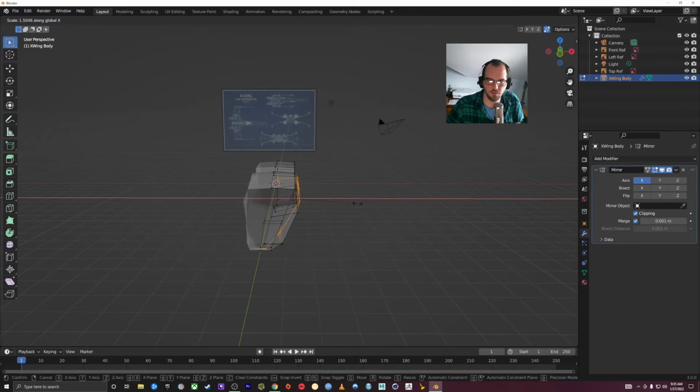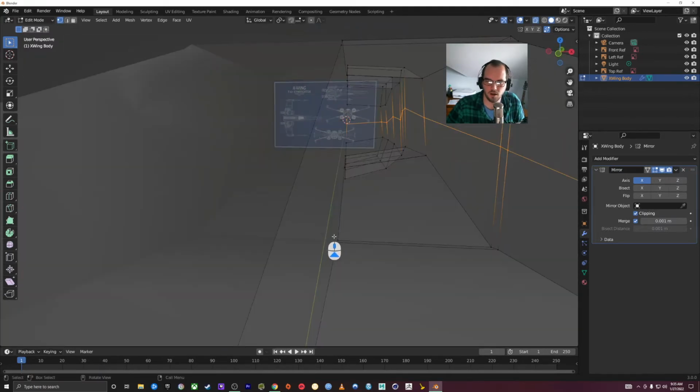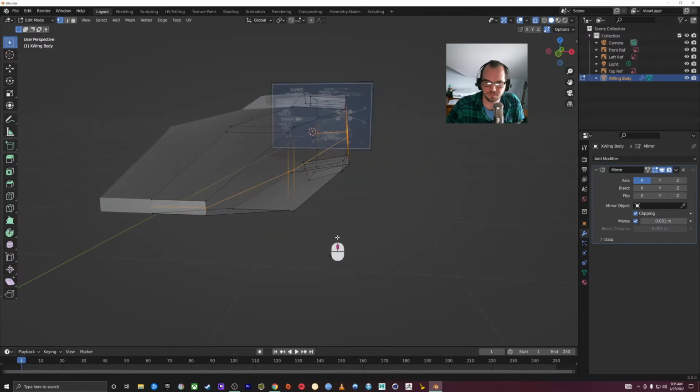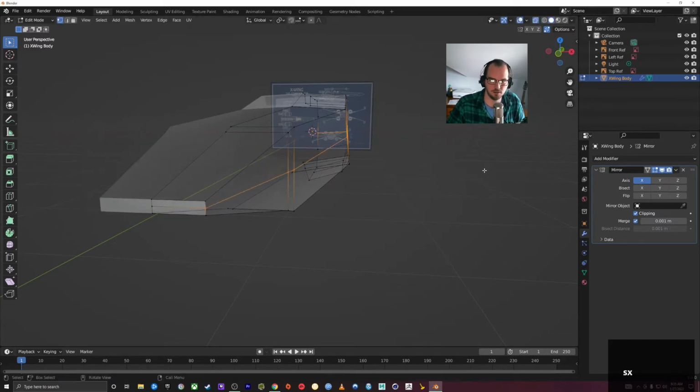And it's being a little bit funky. Can you see how the front is doing the opposite? So I'll just have to go in and fix that. So I'm just going to slide this out. Actually, you know what I'll do is I'll right click, and I've got my selection tool. I'm going to deselect this vertex here. So I'm going to Control click that one to deselect it. So now let me try this. If I SX, it's still doing it. I'm going to Control click this one then too. SX.